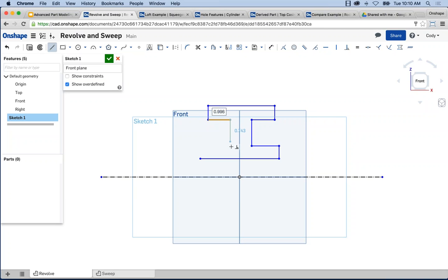So just a tip when sketching, you can wake up any point. Also very useful here, I want a reference to that point on the right. It's not appearing. Move my cursor over it, come back, and now I have the inference. Right. So I've sketched a real simple revolve profile.